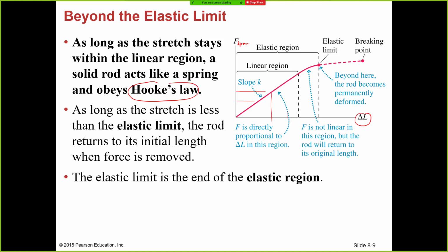That is true only up to a certain point. From this point to that point, you get this linear relationship between distance and spring force, but after that particular point you won't get a linear relationship. It won't be like if you double the length, then the force also doubles.